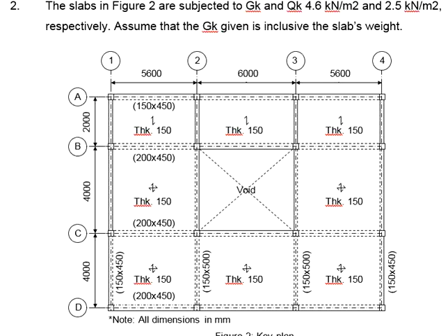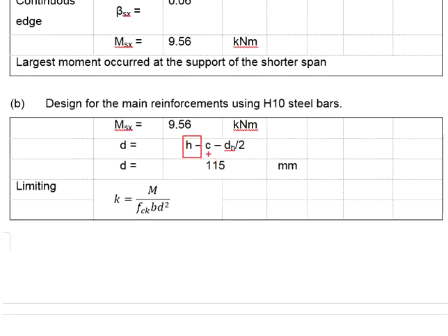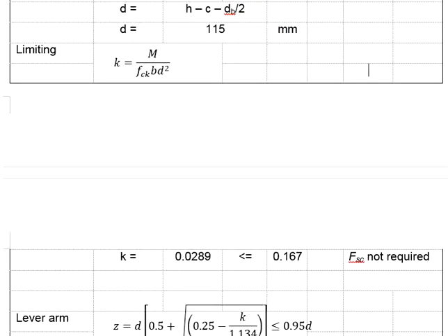Theoretically, there are no restrictions for you to go thinner, but normally we do not see that in the construction industry. Now, if you use a thin slab, this will lead to a very low effective depth. Having low effective depth, you may require more reinforcement bar to reinforce the slab. When the thickness is thin enough, it is still possible to have compression steel bars. But normally we would not do that. Why? Due to the cost of the material.